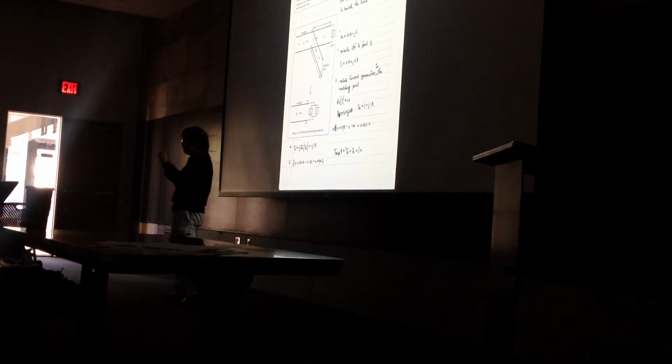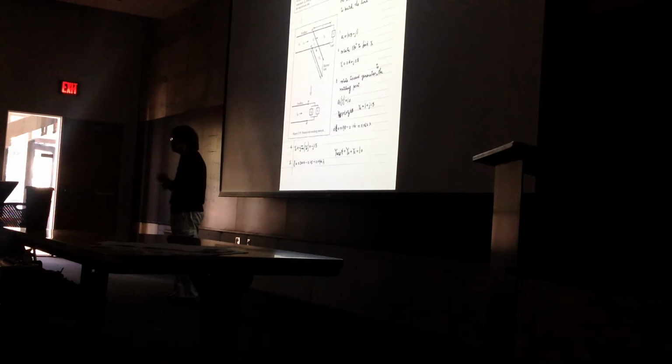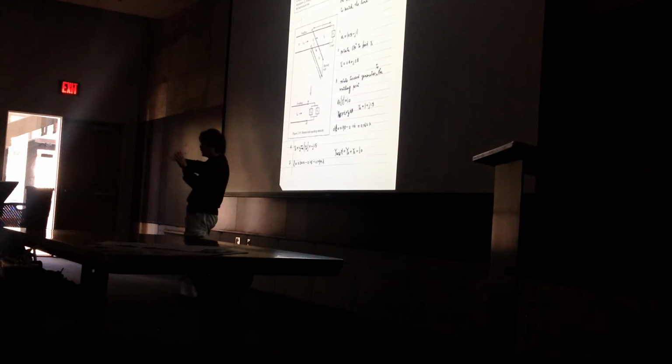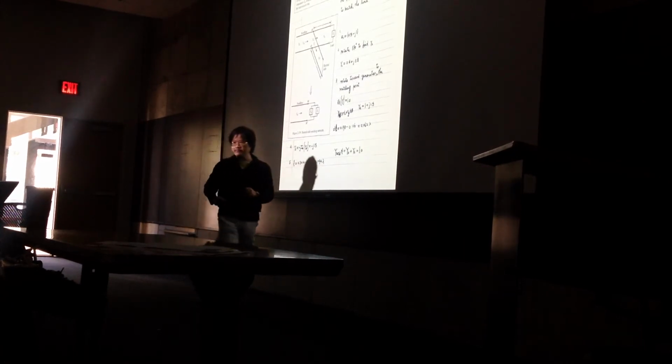How do I find an admittance which has a minus j1.5 to connect to it? So you have already done 50% of your problem. The other 50% is how to make an admittance which is a minus j1.5 to connect to it. Okay? So this is the second problem. Now the first problem is done, so let's go on to the second problem.